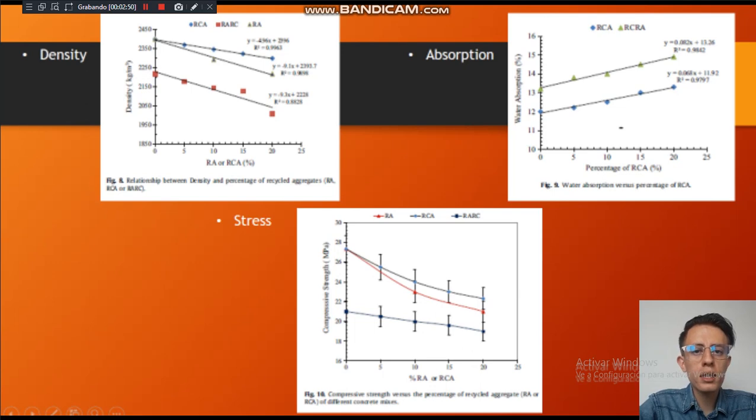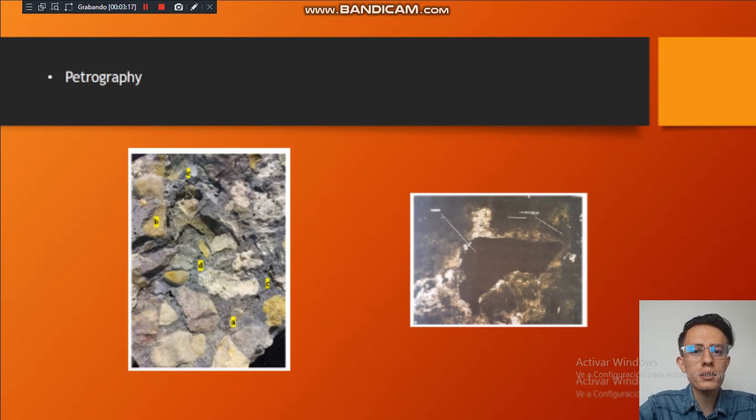Also, the compression test tells us that 25% of RCA can be replaced without significant change in the compressive resistance. It was also found that the percent of reduction of the resistance of a hybrid with respect to conventional concrete can be 19% with a 10% substitution of tire powder. We also have that rubber particles can attract the air since they have the tendency to repel the water. This can cause the reduction in the thermal conductivity with the increase of percent of rubber.